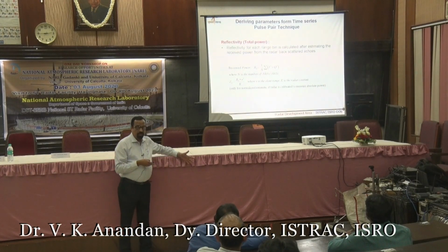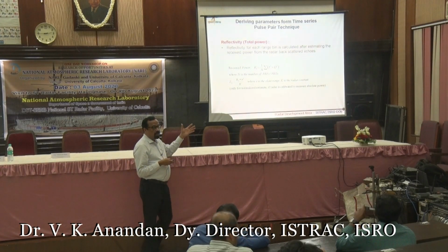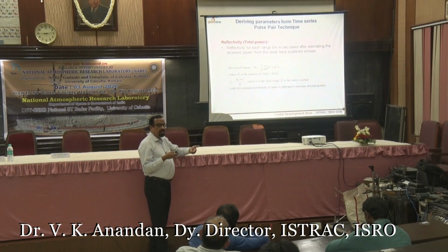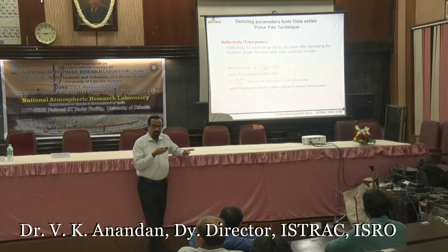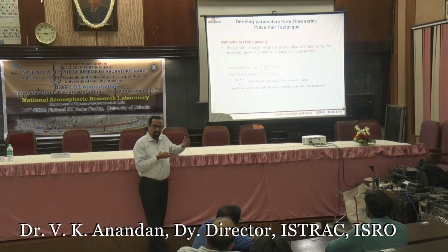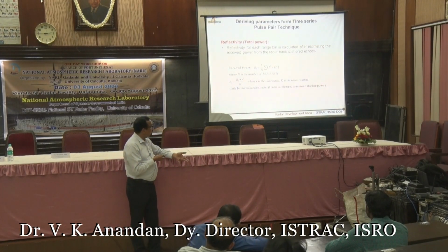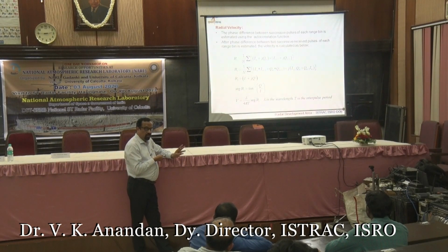And we have another method also. Not only in the time frequency domain what we analyze, we can do it with time based analysis, what we call pulse pair techniques. That means it is nothing but a correlation method of the two signals, which comes originally in your hand. You can do pulse pair computations and retrieve the same information that we retrieve through the Fourier based method. So that's the signal processing part of it. We will get the same information we are talking about: total return signal power, its velocity component, that means Doppler shift, and its variance.